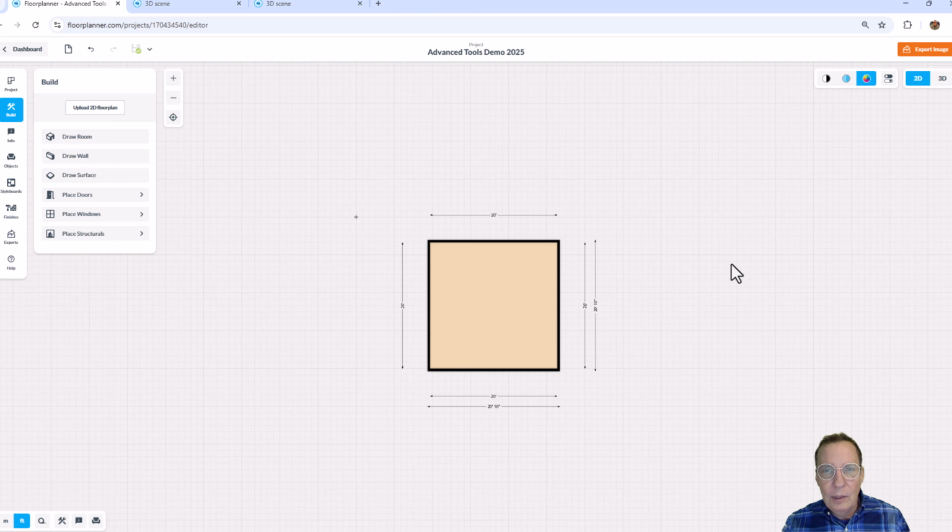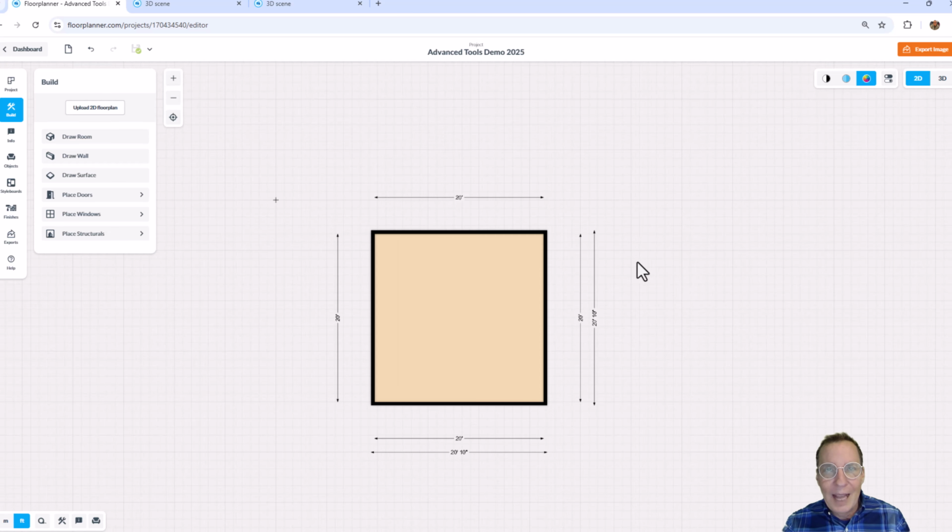So let's take this a little further and take a flat ceiling and turn it into a cathedral ceiling. First, we want to adjust the walls. We want them to slant on the tops. So I'm going to take this wall and this wall, make some modifications, and knowing that there's going to be a ridge line going right across the top center in here. 10-foot high ceilings, maybe take it up to a point at 14 feet high. First thing I want to do is split this wall into two different pieces, equal.